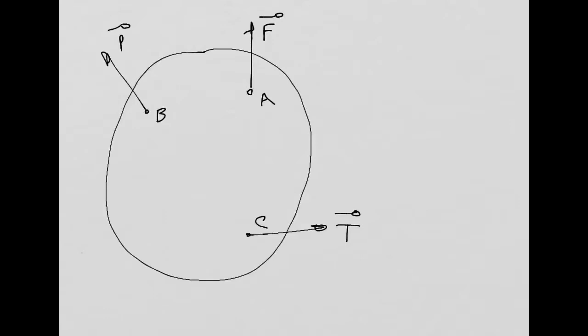So I cannot just come here and say, well, my equilibrium equation is the summation of forces equal to 0. Well, we will need this to study the equilibrium, but it's not enough. The reason is because all these forces are applied at different points, not in a single point like we did last week for the equilibrium of a particle. So I need to have something more to study the equilibrium of 3D rigid bodies.